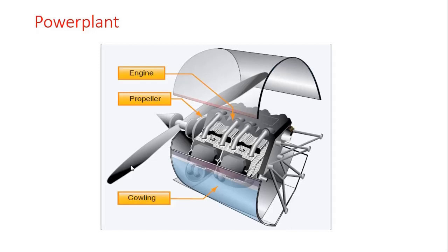These two factors combine to allow a measurement of the propeller's efficiency. Propellers are usually matched to a specific aircraft or power plant combination to achieve the best efficiency at a particular power setting, and they pull or push depending on how the engine is mounted.